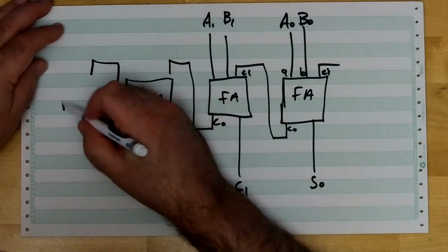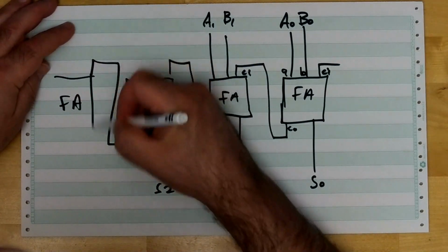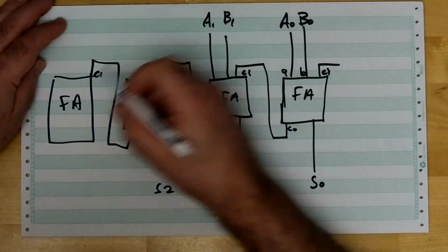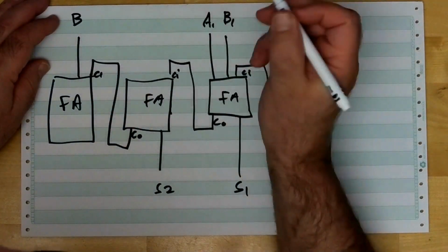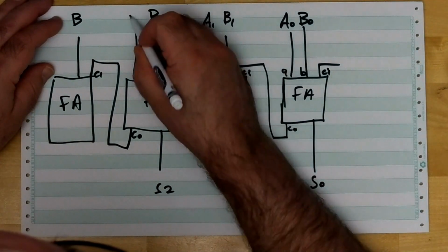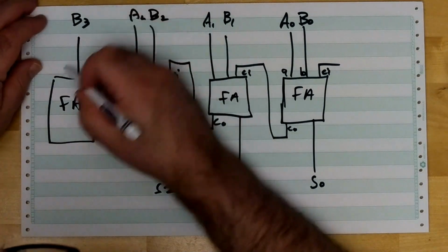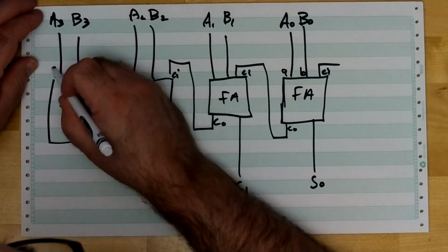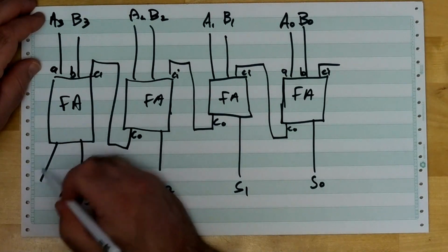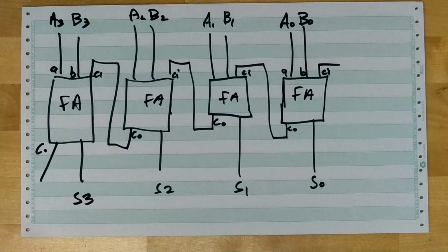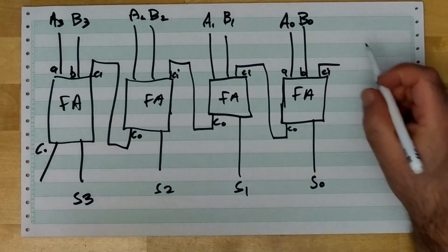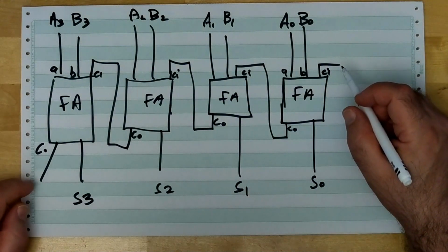Let's just make another 4-bit adder. For sake of completeness, carry in. Carry in. I forgot. Let's not lose track of counting here. B2, A2, B3, and A3, right? Your A input and your B input, your sum for 3, and then you have a carry out over here, okay? Just like when we're adding, you know, 4-bit binary numbers by hand, you always had to worry about this extra carry out over there.